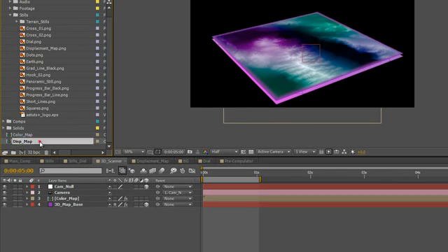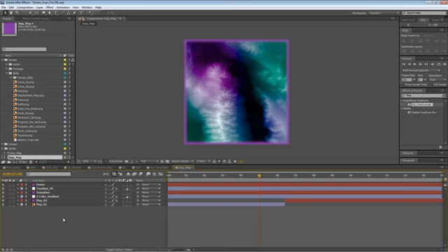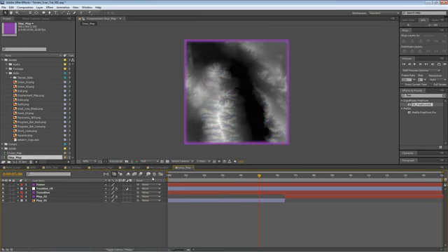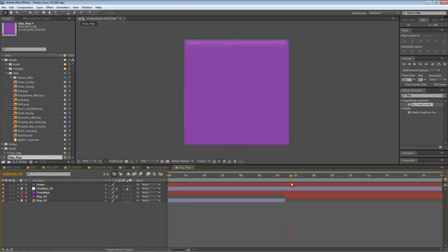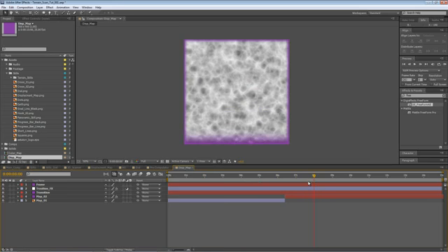And let's open that up. Since we already got everything set up for us, all we need to do at the moment is just delete the 4-color gradient, since we do need to use black and white to displace our terrain scan. And I probably should have mentioned this before, but now is better than ever. I'm using a 32 bits project.